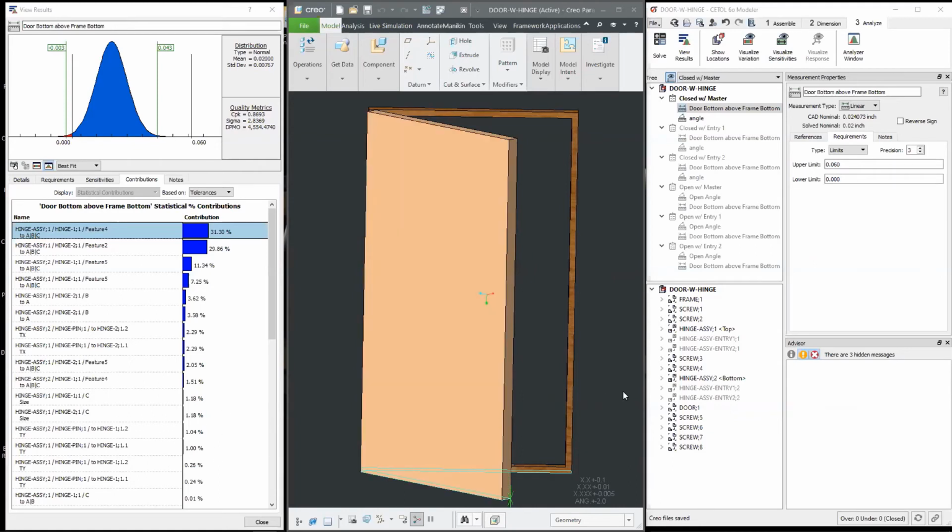Okay. All right. So you see here that we have a CPK of 0.86 with Ryan and my proposal. Standard deviation is just between 7 and 8 thousandths, and so obviously we need to do a little bit of work here. We're going to have some units that rub, but this is kind of a starting point. Let's compare against some of the others that came in.